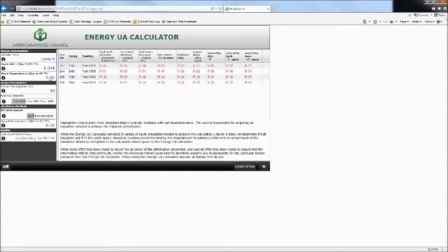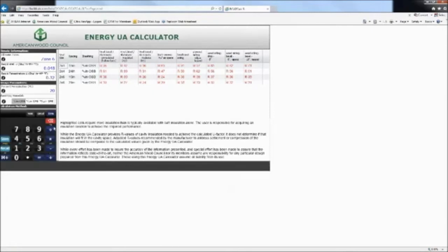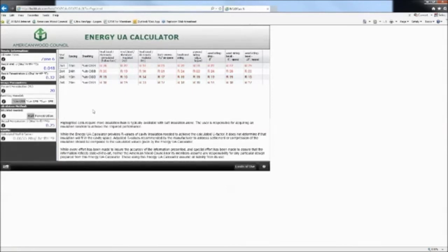And then let's see. So this required wall is 0.048, 0.32, and let's do, I think I've got a 0.25 window at my house. So again, this would come out with a wall U factor right there, 0.0655, and it has the options. So again, in northern climate zones, it's pretty hard to get 2x4s to work sometimes. So oftentimes you'll end up with a 2x6. Great, thanks.